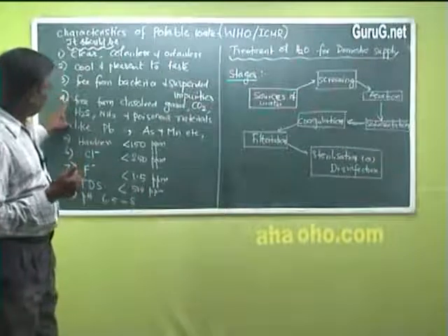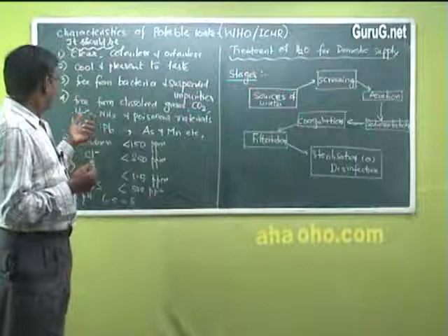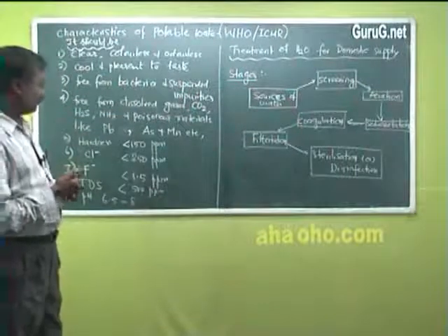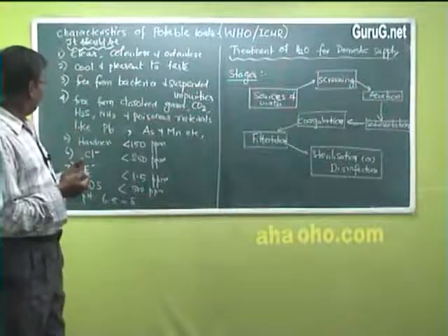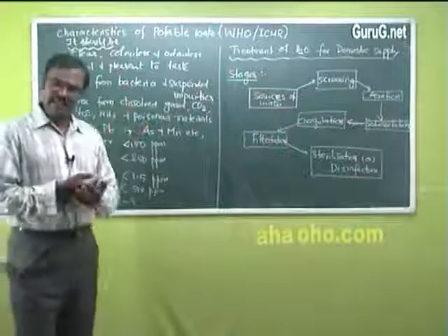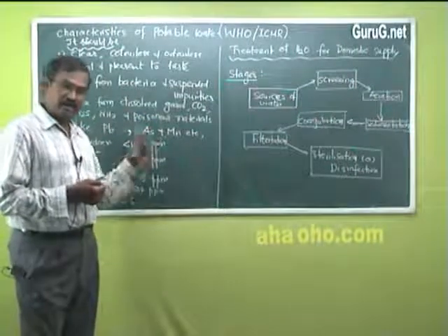And it should be free from dissolved gases like carbon dioxide, which will make the water acidic, hydrogen sulfide, which will give a bad smell, and ammonia also, and some poisonous materials like lead, arsenic, manganese, and so on.